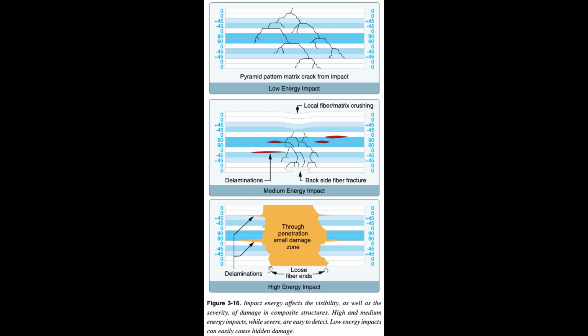Fluid spills on composites. Some owners are concerned about fuel, oil, or hydraulic fluid spills on composite surfaces. These are generally not a problem with modern composites using epoxy resin. Usually, if the spill does not attack the paint, it will not hurt the underlying composite.